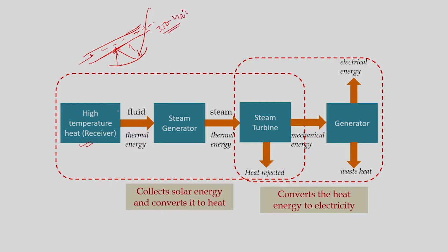Okay? So, the thermic fluid will be heated up, okay, and then that will move to thermal generator or maybe heat exchanger. So, that heat will be utilized and then that heat will be used for heating the secondary fluid, okay, and then it will pass to the steam turbine, okay, because once that fluid what is used in this Rankine cycle will be expanded in the turbine, okay, and that mechanical energy can be converted to electrical energy by using this generator, right. So, of course heat rejection will be there from the turbine. So this will work in a closed loop.